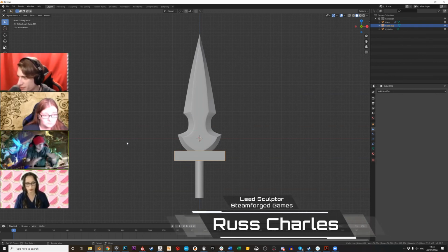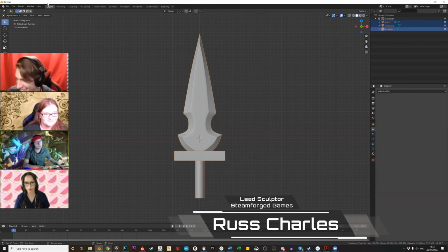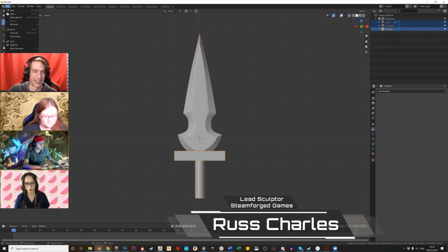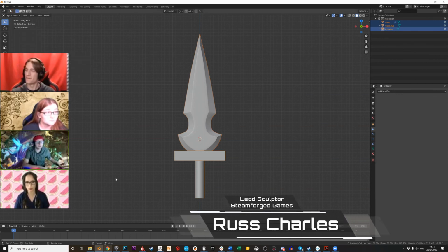And the great thing is, if you wanted to print this, Lord knows why, but if you did, you just shift select those, export them all as a 3D object as a group, and then when you load that into Netfabb or Meshmixer or whatever program you use to prepare your print files, it will automatically see that as one object. When you run that through your normal mesh cleanup, it'll delete out all the missing vertices and turn it into one piece, and then that will just print as a sword ready to go with the handle and the guard and the blade all together.